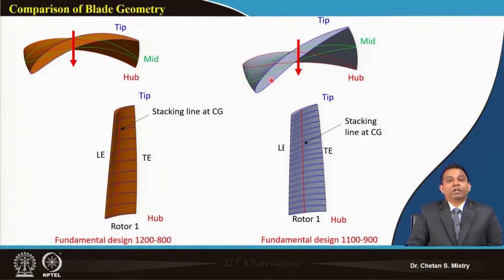Many times in the initial design, people work with axial entry, then they realize they are looking for a particular kind of performance that they may or may not be achieving. At that time, span wise they do their calculation for total pressure rise, and based on that comparison, according to the expectation, my delta P0 can be changed.